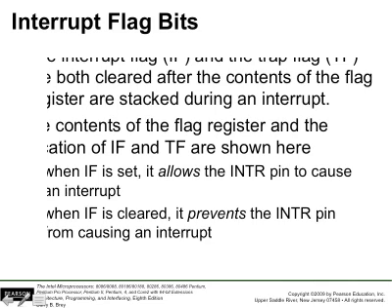We have these two flag bits in the flags register that are used closely by these interrupt service routines: the interrupt flag and then the trap flag. After we push the flag register onto the stack, at the beginning of the interrupt responding procedure, we'll clear these two.